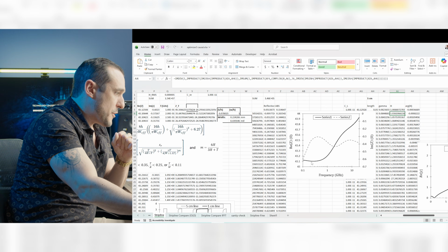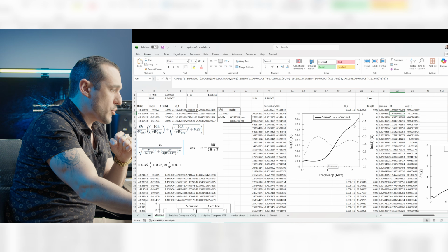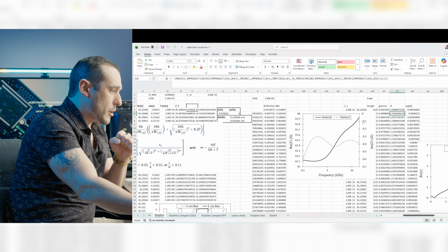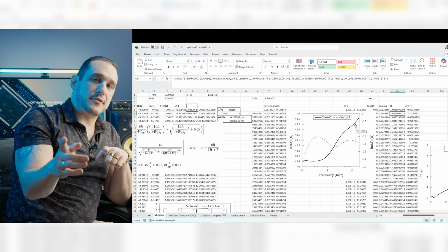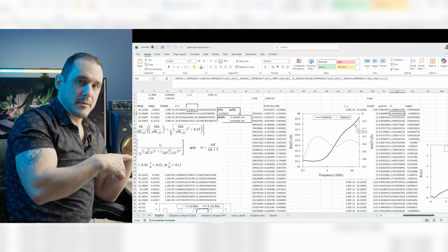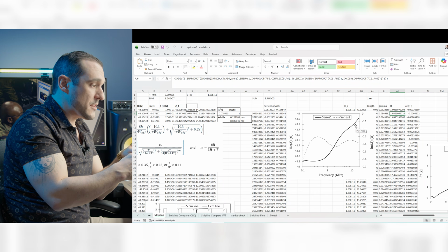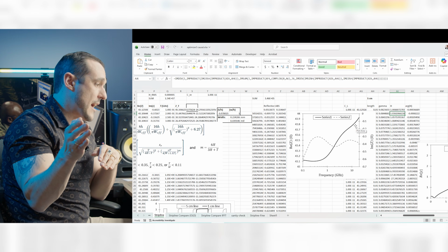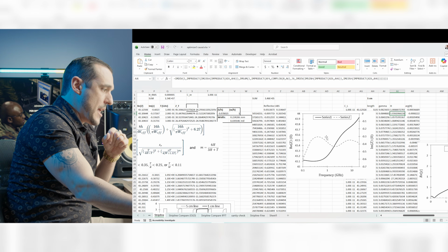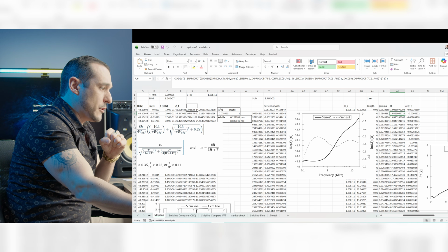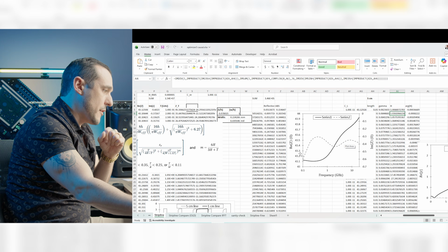You can see that the real part of the impedance tends to increase in this upward curve fashion, and this is exactly what I've shown in some other videos on the Altium Academy channel and on my channel when you look at the impedance once you start to include these other loss factors. You can then see here on the right hand side the scale for the imaginary part, and the dashed line here shows the imaginary part of this impedance.